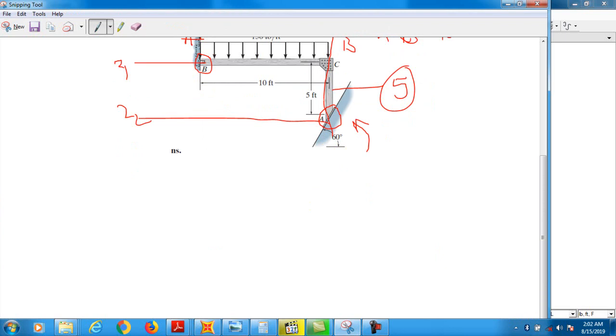Determinate beams are simple. Indeterminate beams are a little bit complicated. But you must know the steps are the same. We draw the model, assign the joints and loads, and then we analyze. Determinate structures or beams are those which can be analyzed by using the equations of equilibrium, and indeterminate structures are those which can't be analyzed using the equations of equilibrium.